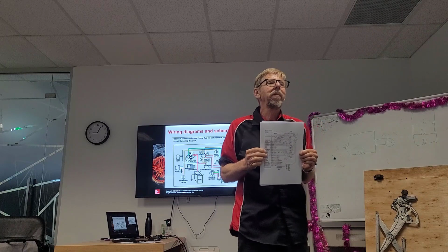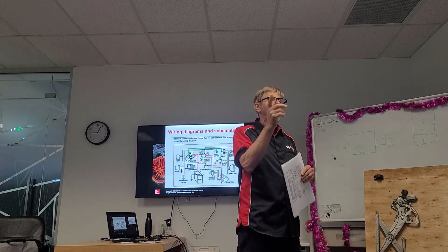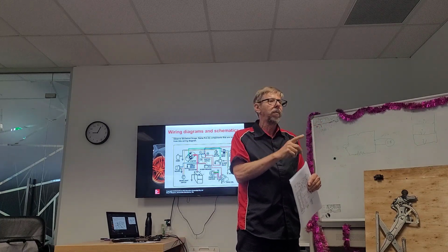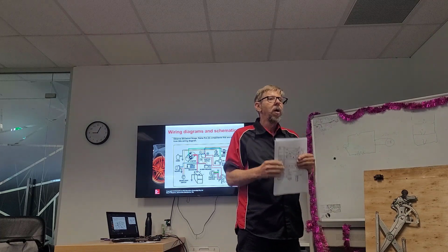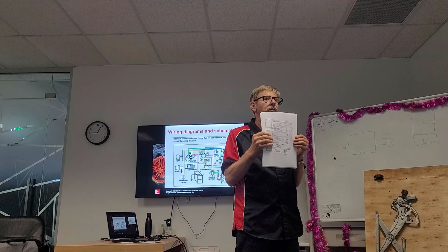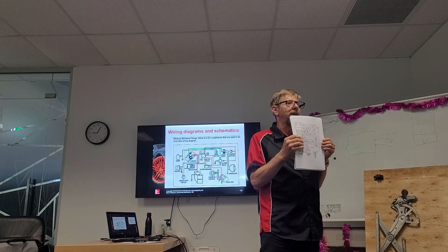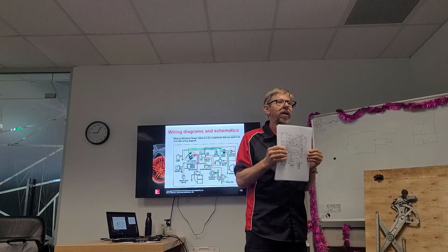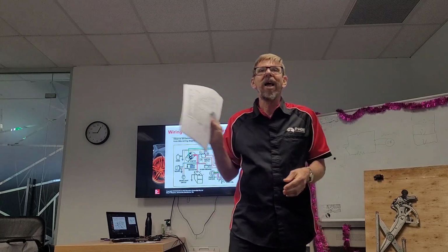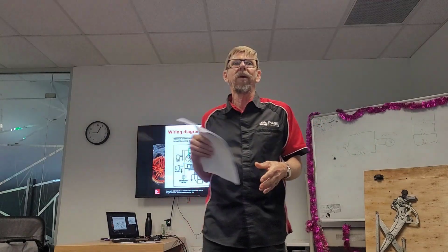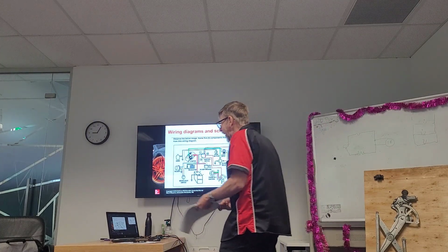But if we remember, we broke down our circuit recently for a single parallel circuit. We looked at one circuit. We can break that down into those sort of circuits, just the simple circuits, okay, even though they're looking complicated. And that's what I'm trying to instill into you guys, is how to look at and read a wiring diagram, okay? That's my objective today.